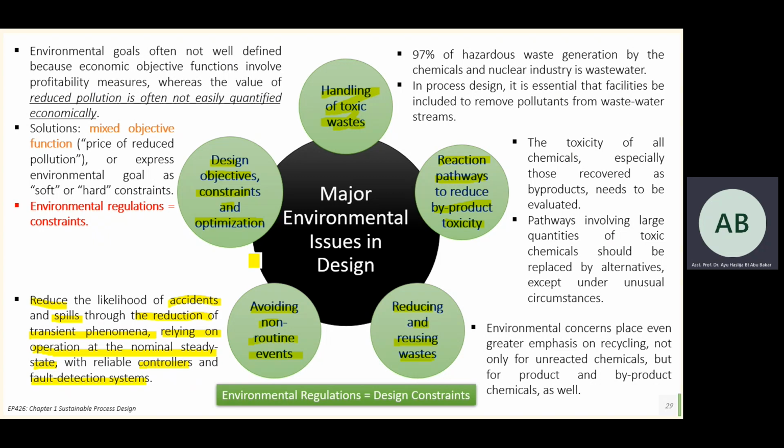What is your product from each process? From there you can see what waste you are producing from the flowchart already. PNID is after you settle with your PFD. You confirm on everything, all streams, then only you move to PNID. Okay.